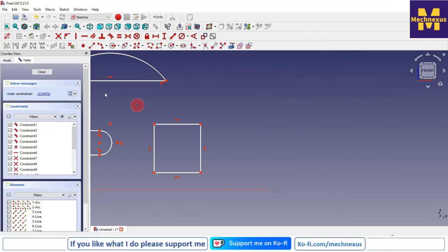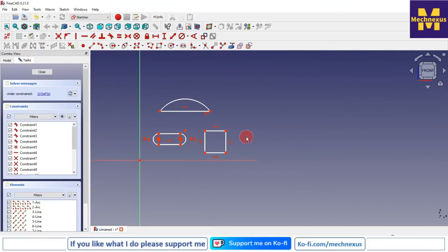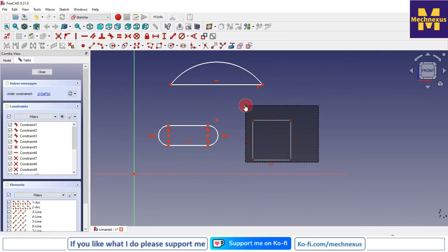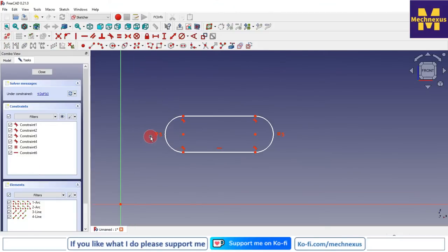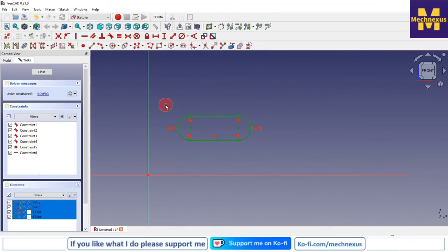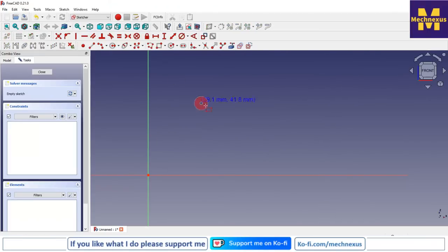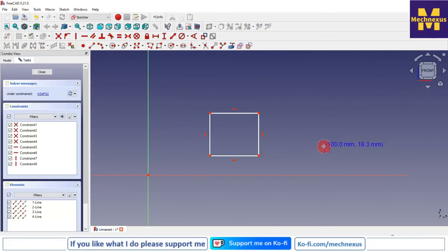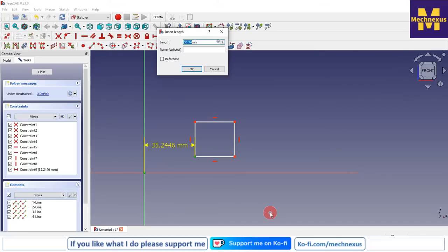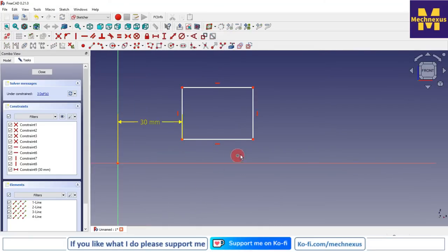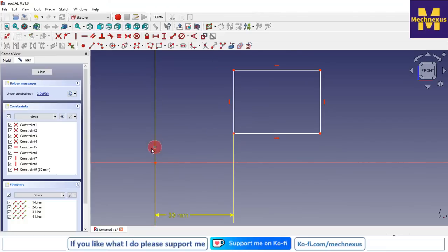Now we will understand the next tool, which is Symmetric. For this we will delete this rectangle, this sketch, and also this slot, and we will simply create a rectangle. Now we will give the dimensions. From this point to this point, I give 30 horizontal, and I will give 30 vertical as well.